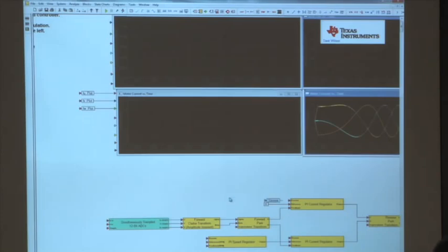So I'm going to put it on the input of the PI current regulator. I'm going to do another Control V, put it on the other PI regulator. Where else did I need it? Oh, the speed loop, Control V. Okay. Once I've done that, connect from the output of the sample signal into the inputs of those execute pins, as I've done here. So now those software routines know when to run, which is synchronized to the PWM module.